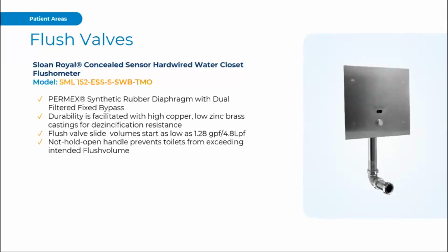And then we enter that same flow rate discussion, because as I mentioned in the tank type portion, these can range from 6 liters to 4.8 liters down to 4.2 liters, or 1.1 gallons per flush. So the earlier in the design process that we can raise this question or provide the options and get the revisions is always the better.